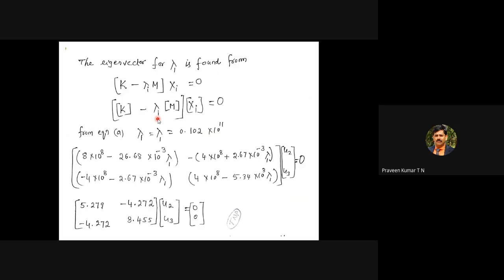There are two modes of vibration, the first mode of vibration as well as the second mode of vibration. The first mode of vibration, where it just moves forward and backward, is referred to as rigid body motion. And in the second mode of vibration, there may be flexing or twisting of the bar, which is normally referred to as flexing of the bar. So that we'll discuss later. So we have two values for the lambda. In simple terms, we have lambda i, with two values.